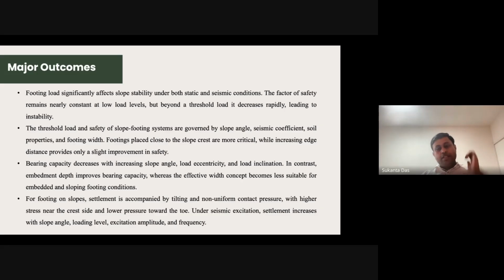Bearing capacity decreases with the slope angle and loading intensity. So that also we have discussed. Though I have mentioned the embedded depth here, it was not presented much. But what I discussed is that an effective rule cannot be implemented, so I will recommend using our charts for the site engineers.